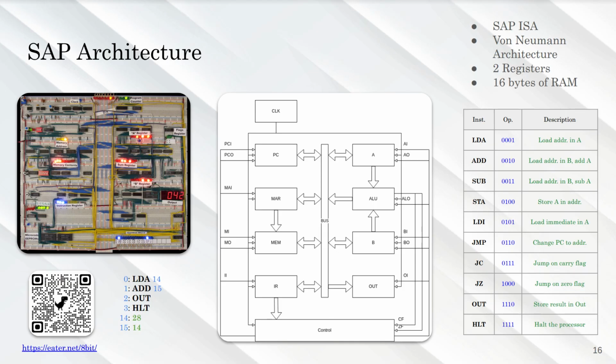That's great. So finally, we have these two little instructions. The out, which is just like a printf, is going to say, okay, now the value that is on the bus is going to be stored in the out register. And finally, you have the halt. The halt, as its name suggests, is just to say, okay, we can stop the processor.